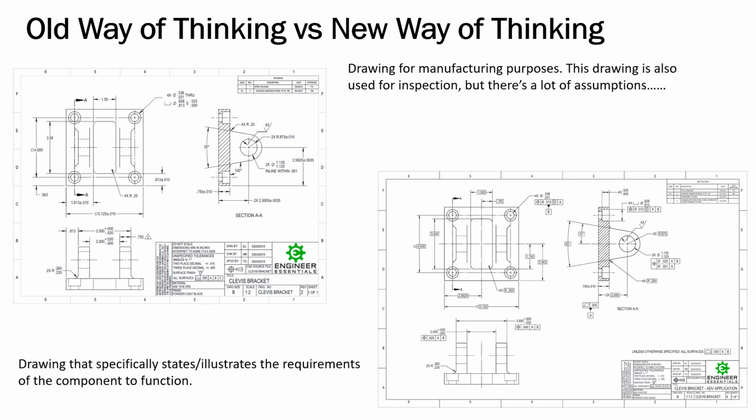I've worked with engineers whose plan of attack on a drawing is to go in there and just load it up with GD&T, a lot of complex GD&T, and that's not the point of this. We want to make sure that we're not sending anything out to the floor that can't be made, or something that would have to go to a CMM to be inspected, but our quality department doesn't even have a CMM. If we're a company that is constantly contracting CMM work out, okay. But if we're sending it to our inspection department and forcing them to inspect it, what are they supposed to do if they don't have this CMM?